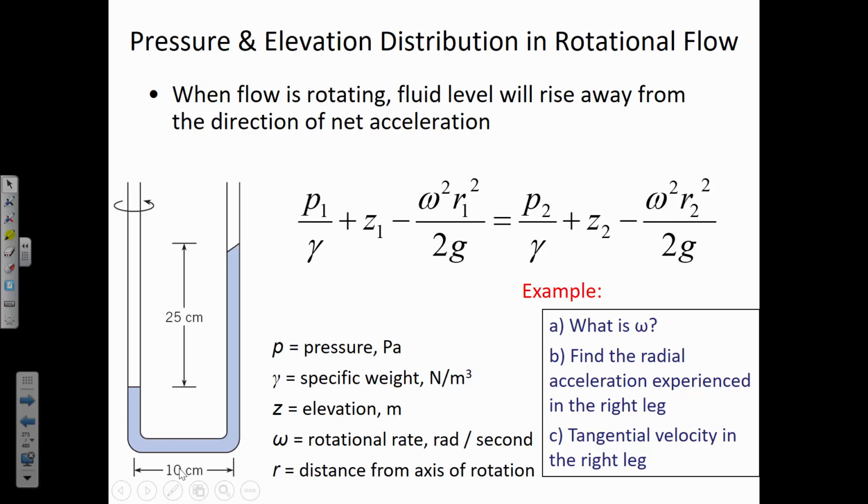And then what do you suppose we know about the pressure at this interface between the liquid inside of the U-tube and the gas that is open to the atmosphere? Zero pressure. So we're going to say, let's work in gauge here, relative to the atmosphere. And so here at the opening and the interface of the liquid and the gas, the pressure at 1 is 0. And we can make location 2 be this spot where it's the free surface of water.